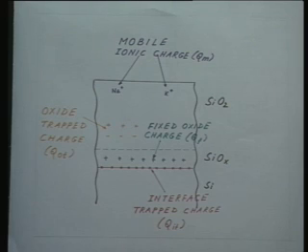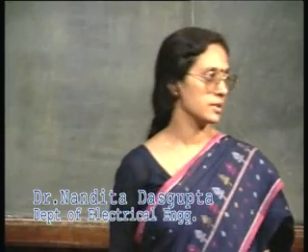Then we can have, all over the oxide, positive or negative oxide trap charges which are present because of maybe exposure to the radiation environment or because of avalanche injection. And finally, we can have mobile ionic charges which are free to move all around inside the oxide and which are usually a result of human body contamination or contaminated water. Since these charges decide the quality of the oxide, it is imperative to minimize them. So, how does one minimize these charges?